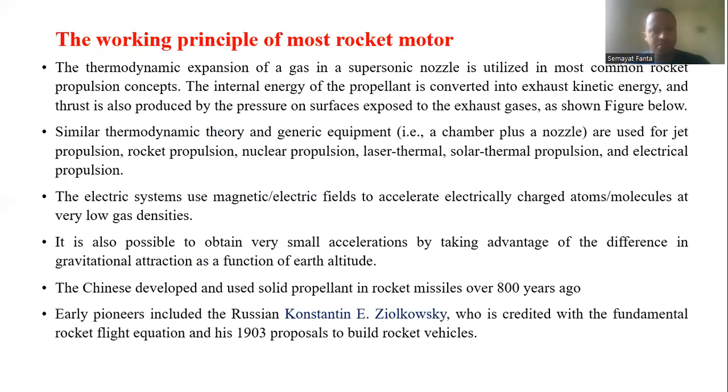And what is the working principle of most rockets? When I am talking here, overall rockets. The thermodynamic expansion of gas in a supersonic nozzle is utilized in most rocket propulsion concepts. The internal energy of the propellant is converted into exhaust kinetic energy. Look, we have chemical energy that will be changed into kinetic energy, and then it is converted into thrust, which is also produced by the pressure on surfaces exposed to the exhaust gases.